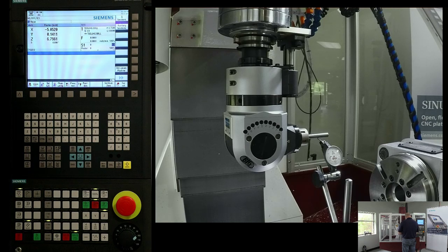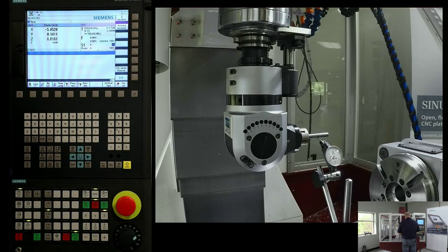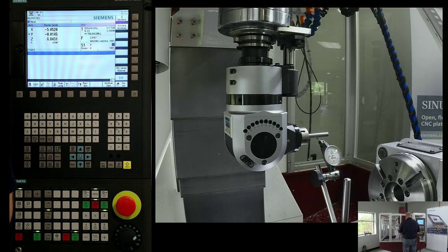So when you're using an indicator on this type of application, it's worth noting that I have to find the high spot of the bar first. I want to set my indicator dead center of this bar. So if you just start to engage on the indicator, and now I'm going to move the perpendicular axis to the bar, in and out, and what I'm looking for is the high spot, and I'm into it quite a bit, so I'm going to bring up my Z a little bit. Because what I'm looking for is the highest point before the indicator drops.